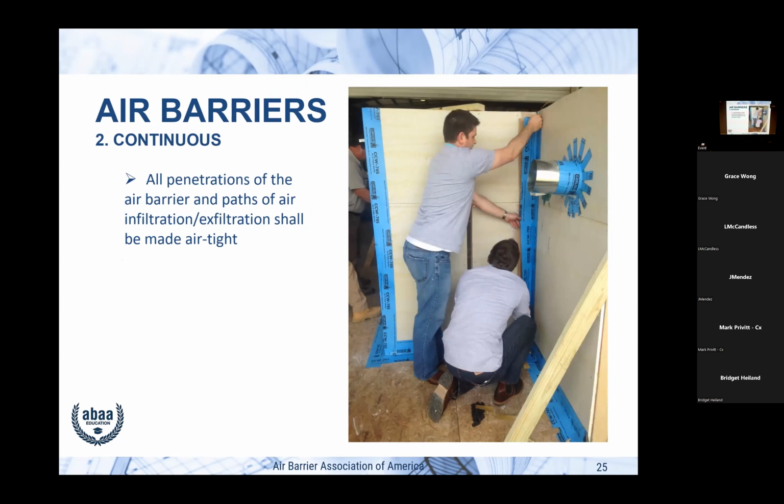Talked about penetrations coming through walls and so on and how they can leak. So this is part of our training course for installers. You can see they're putting transition membranes on inside and outside corners because those 2 walls can move. And then you see a pipe coming through with, I don't know what the person's done. That's the first impression, but that's the proper way of making that seal because you want that pipe to be able to move back and forth without breaking the seal.